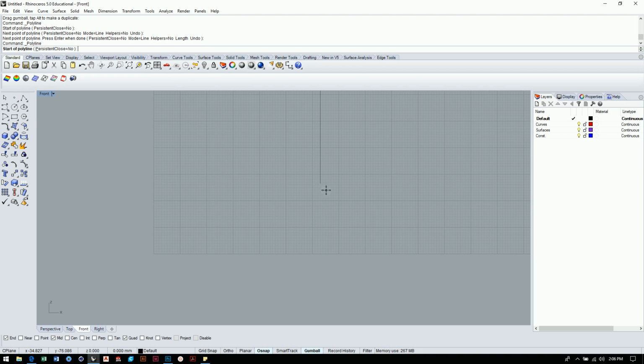I'm going to go ahead and just attach a polyline right to the end here, and then I'm going to type in 20, which is the measurement down we need to go. And I'll just drop this kind of anywhere.